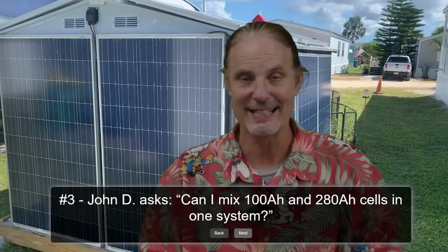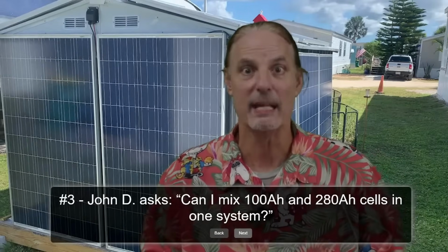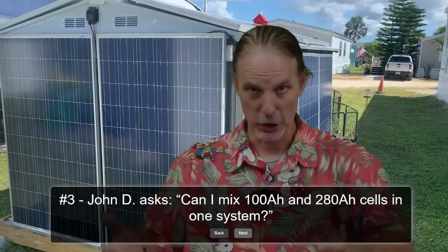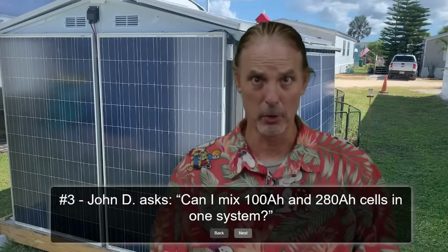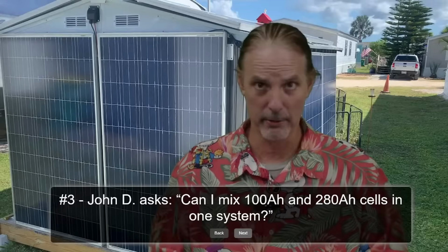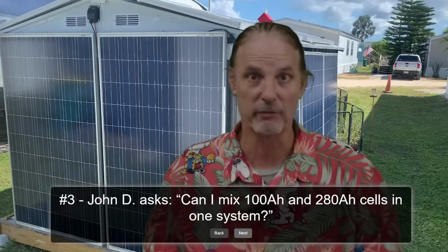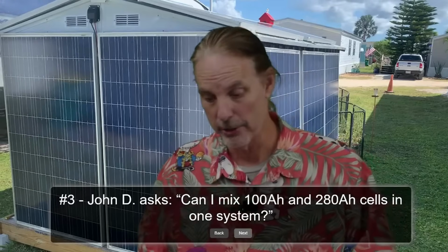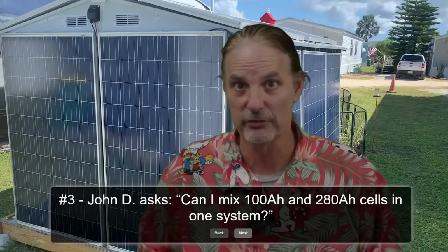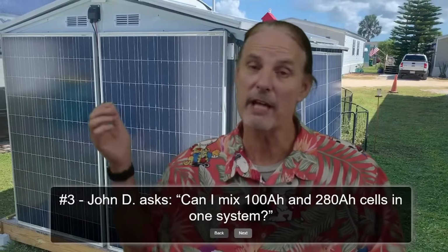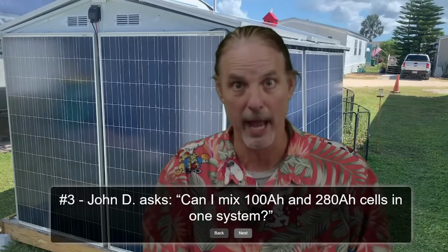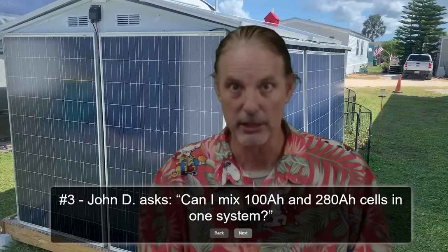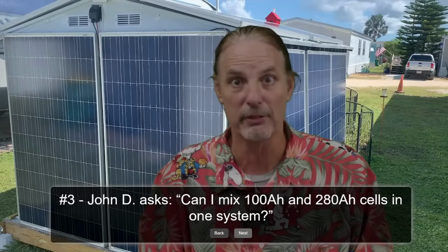It would be very easy to have a bank of 10 batteries get a huge influx from a brand new battery that gets pulled and have all 10 of them pulling on it. If those 10 batteries are low voltage, say 52 volts, and the new battery you're hooking up is fully charged at 56 volts, and you flip it on, you could have 10 batteries all try to pull power from that one large battery, and it could easily cause it problems if it's not properly fused.